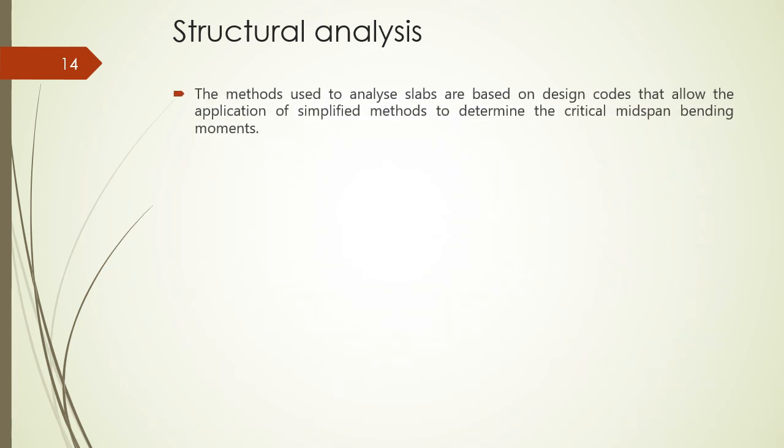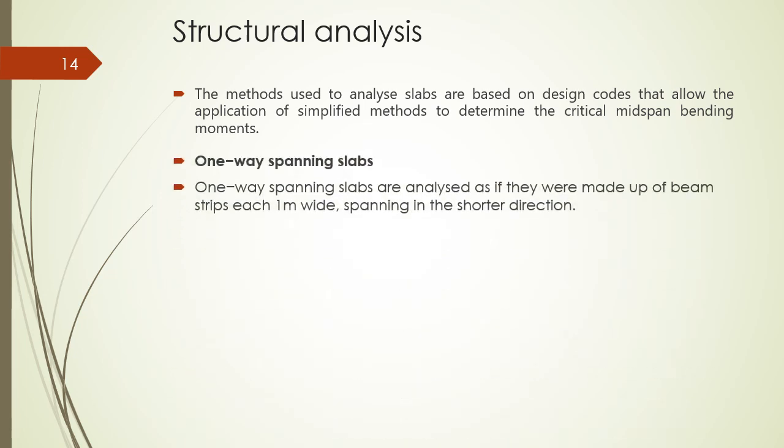The methods used to analyze slabs are based on design codes that allow the application of simplified methods to determine the critical mid-span bending moment. One-way spanning slabs are analyzed as if they were made up of beam strips each 1 meter wide.